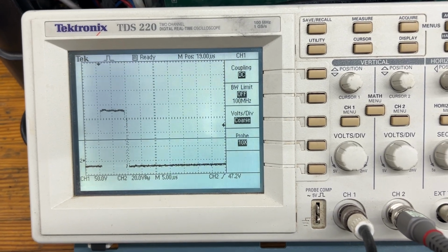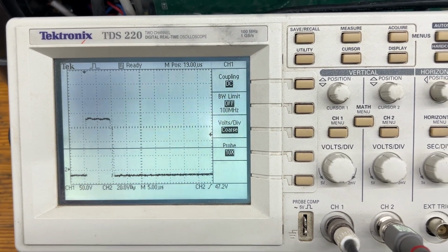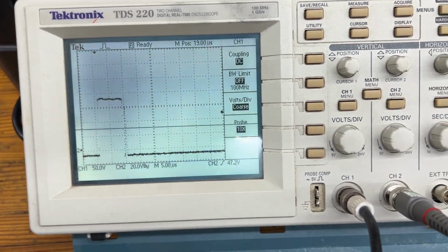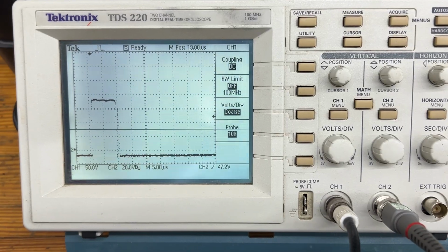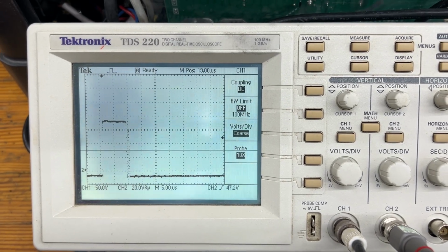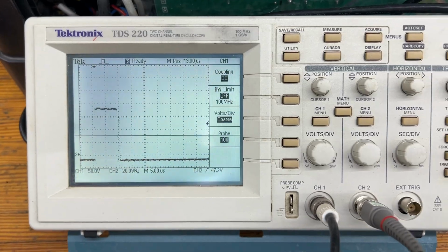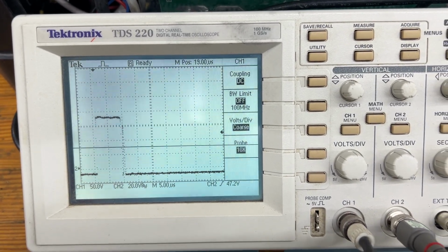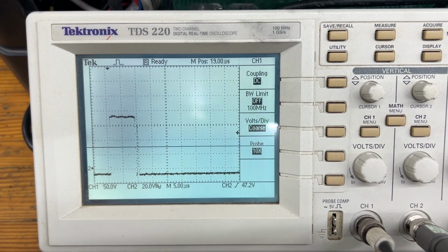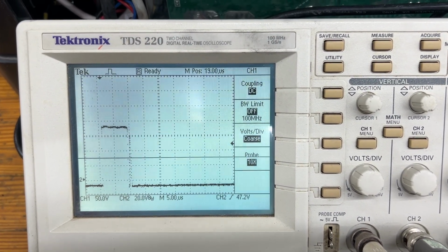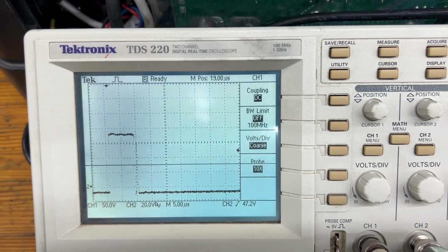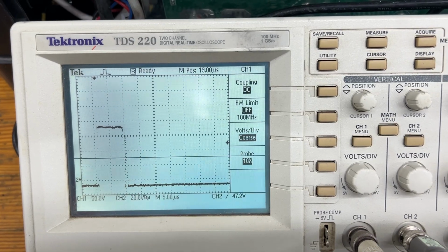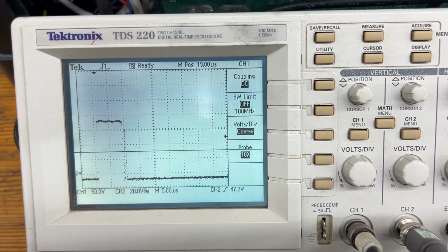Okay, we're continuing to debug the wire feed speed problem. We replaced the relay, which improves the situation, so now the motor starts immediately when the trigger's pulled. But now it's behaving such that it has an initial RPM speed, and then after a few seconds it increases to another higher RPM speed.